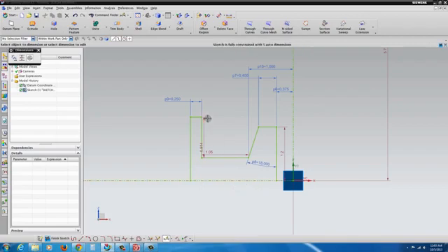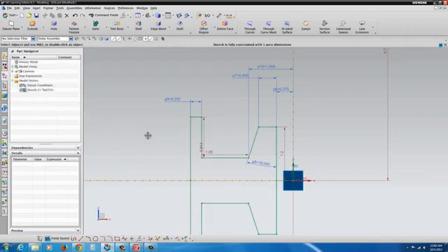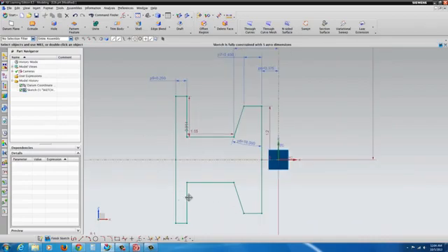Okay, now to mirror it. If we go down here, we can click on this little arrow to the right and find the mirror curve. What we're going to do is click and drag a fence to surround what we want to mirror. And then for the center line entity, you click on this button. Select the center line and hit OK. So now we have the symmetric geometry on the other side, which we can continue to add our dimensions to.